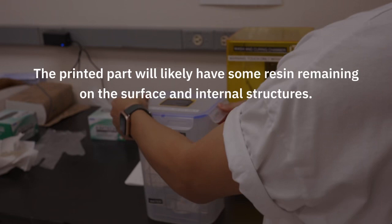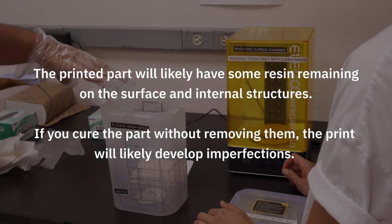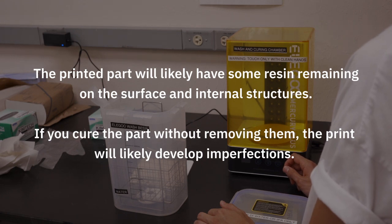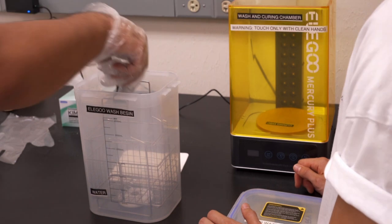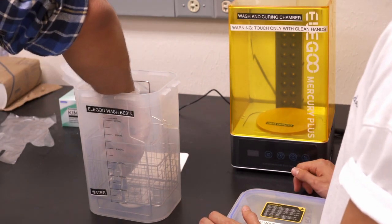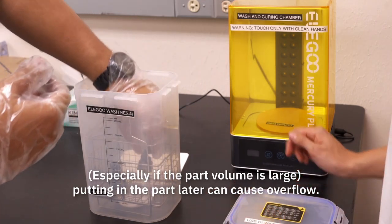Post-processing is a very important step where you wash and cure the part that was printed. Here, we are removing the resin that is still on the printed part before curing it globally with UV light to make it completely solid. First, place the parts on the metal rack inside the cleaning tank. Always put the part in first and then pour the washing solution.